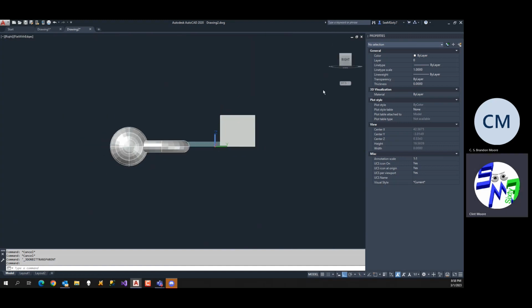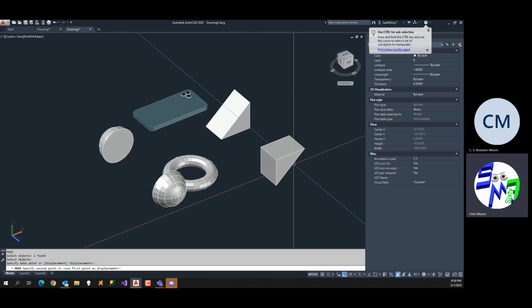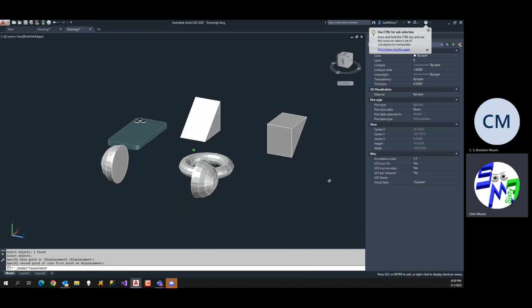I'm going to cheat and create a UCS. I want this UCS here, so I type in UCS, and this is the view I'm on, so I hit V for view. Then I select slice and pick here, and now it's just looking for 2 points. I can say from here to the endpoint here. Now I'm done. I can grab this, and now it's a wedge. There are all kinds of things you can do and build with these.